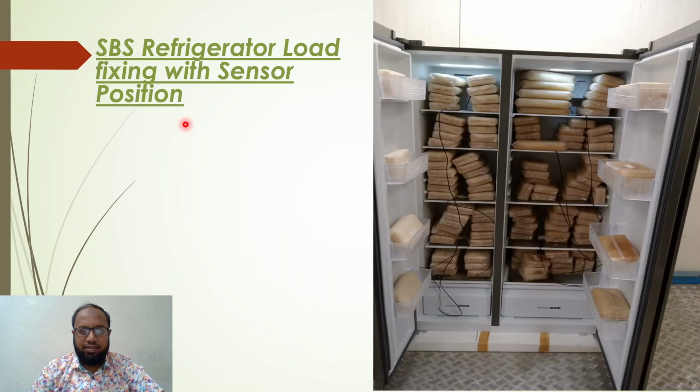Then, as I discussed for the side-by-side refrigerator, this is the load test of this refrigerator. After fixing the sensor, we put the load in the refrigerator. You can see here the load of the refrigerator we are using for performance testing purposes. On this side is the refrigerator chamber, as I discussed previously, and this is the freezer chamber of this refrigerator. Here we are putting a 34 kg load, and here a 33.5 kg load.